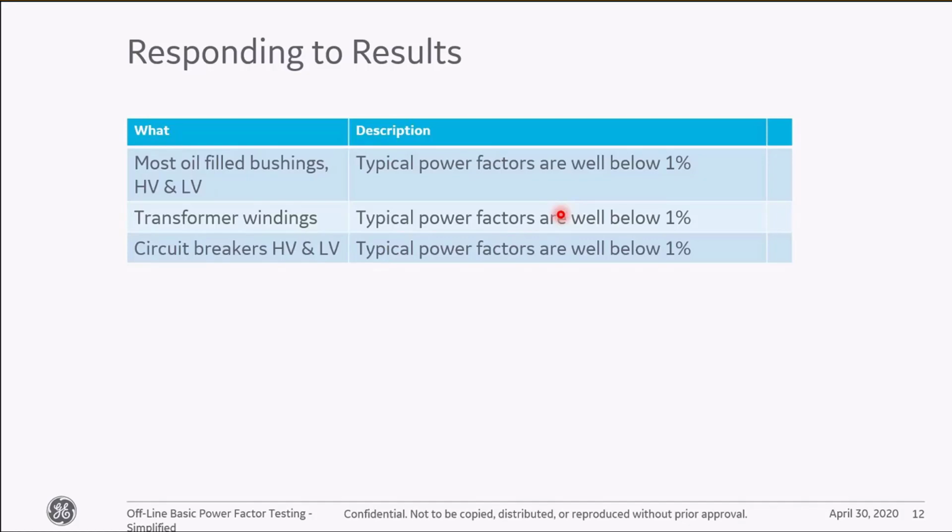So when you talk about these high voltage capacitors and these low voltage capacitors that we have in substations in the form of bushings, in the form of windings on a transformer, when you short them together, you see them up there shorting the high side out. Well, why are they doing that? Well, they need to make one piece of copper there. And all the insulation that's associated with that piece of copper will be measured to earth. And they will look between those two conductors and calculate the power factor. Or these days, the test equipment will do it for you.